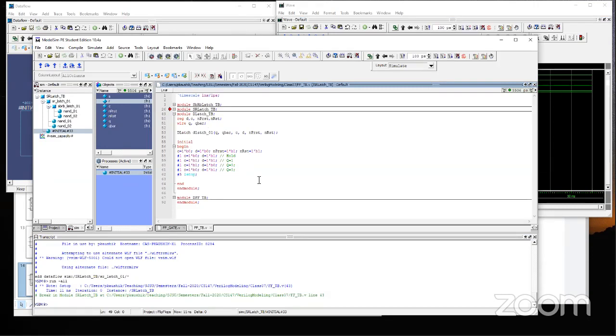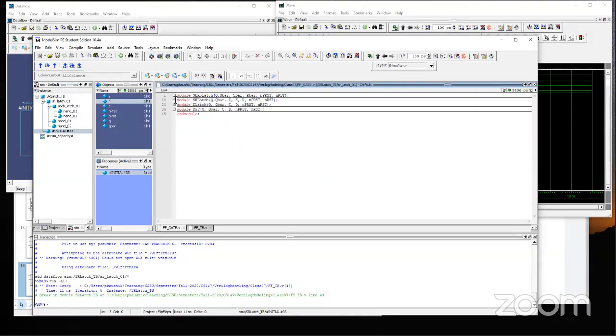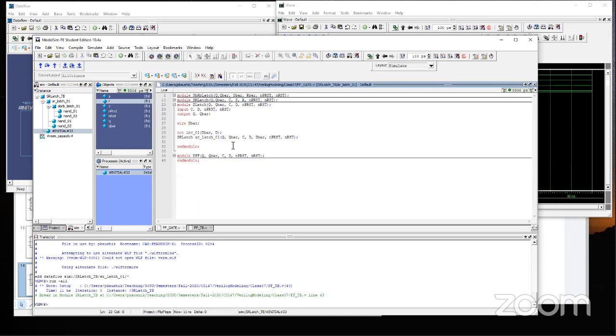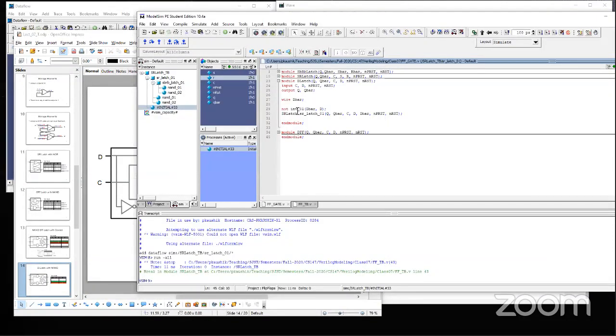Oh no, that's the test bench. SBar RBar. Okay, let's open this up. So now we basically have an incoming D, which is this one, and it gets inverted through an inverter instantiation, inf1, and then we feed this D and D bar in place of S and R of the SR latch.